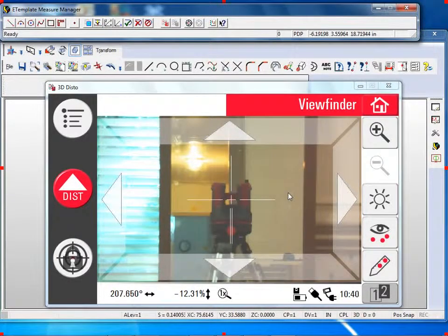The laser has online video through the head of the laser, which is what we're seeing here. I'm pointing towards a mirror so we can see it within the video. And this crosshair represents the exact measurement position of the laser. In the video we do not see the red beam. At the job site you do, which aids in your visualization process. But the crosshair is very important as well for being able to align spaces and locations further away.